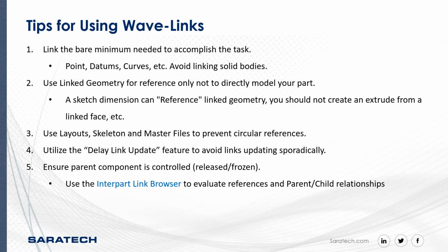Ensure the parent component is controlled. So this can be released, frozen. You want to make sure that if you're linking to an interface, for example, or bolt pattern, and you release that, that bolt pattern should not change, right? That should be released, that should be frozen. You shouldn't be releasing something where the dependency of that is still being worked. So again, this is where Teamcenter is critical, and having a controlled environment is critical.